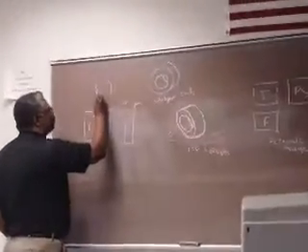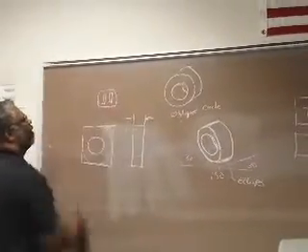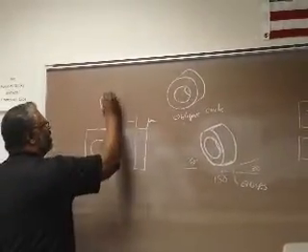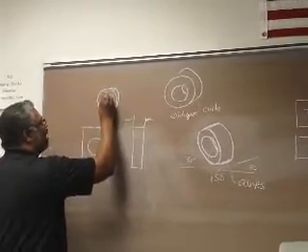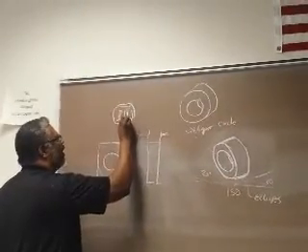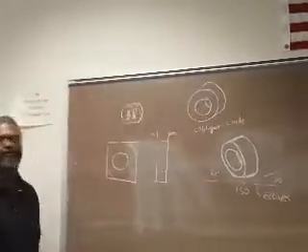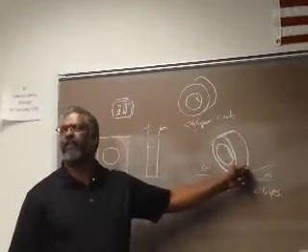And if you draw that as an orthographic view right here, it's easy to copy that and then just give it a thickness right here, and then copy that and show your thickness of that material right there, and then you got that little outlet right there. To draw that as an ISO would be more complicated.